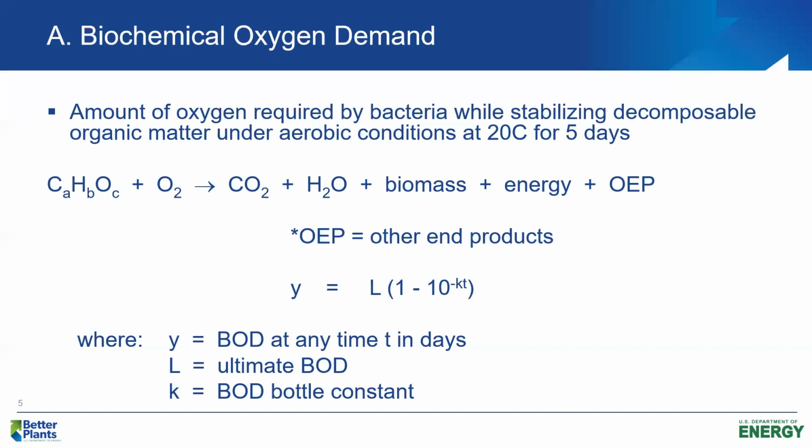So when organic matter is oxidized to carbon dioxide, water, energy, and other end products, that generates energy for the bacterial cell. And I may use the human body as an analogy to help you get a better feel for biological treatment. But this reaction is going on in your body right now. And this reaction is what's keeping you alive right now. You've got to have energy, and you've got to produce new cells to replace those cells that are dying in your body. And the average adult human has 70 trillion cells in their body. So again, this is an important biochemical reaction for you and for me.